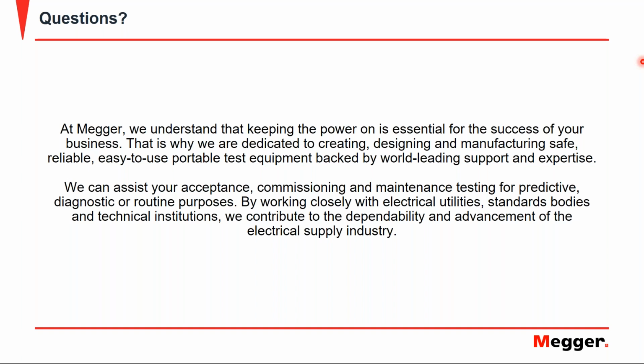That is a good question. Nowadays, most cables which are installed are polymer insulated cables, so mainly XLPE. And those cables should be pre-tested at the manufacturer already. So if those cables are installed, then the main issues we identify, I would say 90% or probably 99% of the cases, the problems will be in the accessories because they are man-made and mistakes can be made.